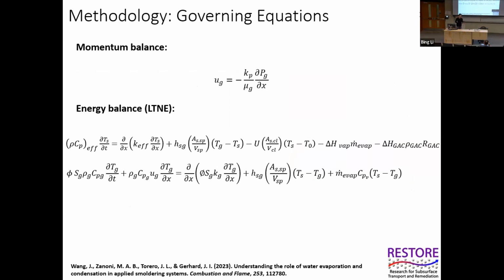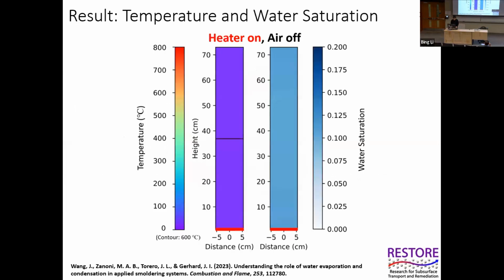And the momentum balance, basically the velocity of the gas, was solved by Darcy's law. And we use two different energy equations to solve the temperature of the sand and the temperature of the gas. We used COMSOL software to solve all these equations, and now it takes about 2 days to finish each simulation. So this is the simulated results.